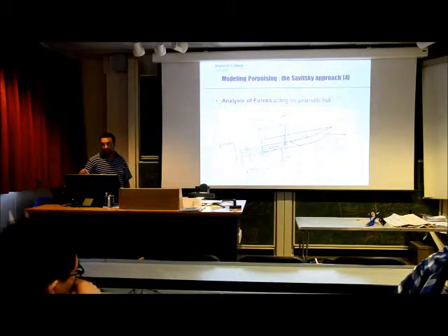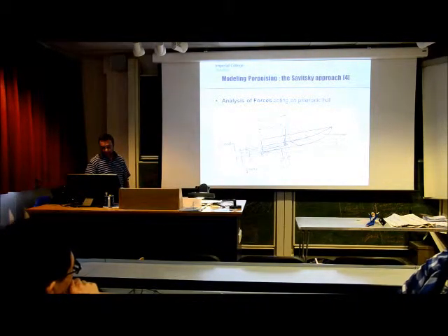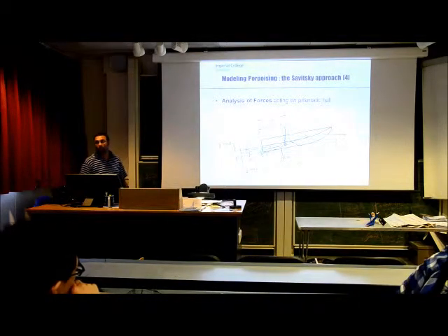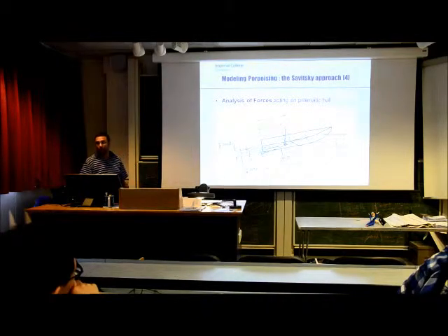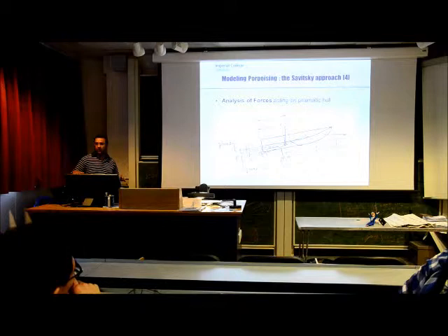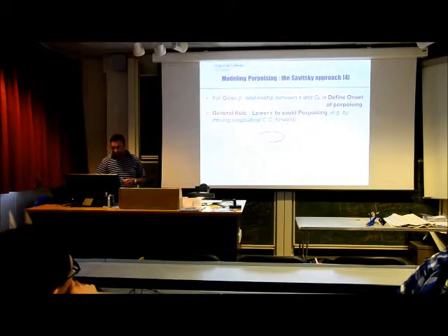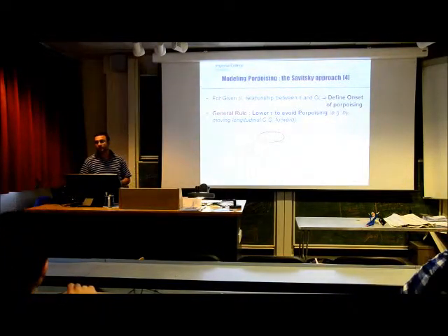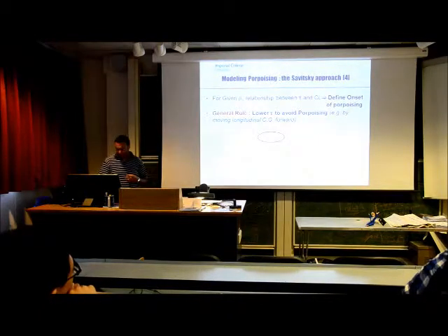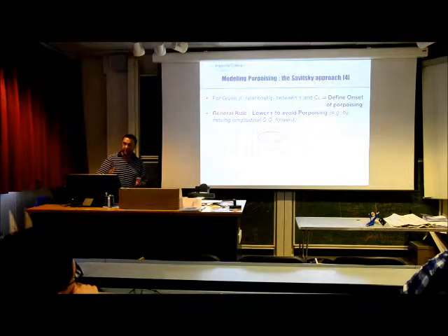I mean, any upward forces acting on the wing are accounted for, because this is like a racing boat model basically, and they have lifting devices as well. Okay, so that CL that goes in the graph is the lift coefficient associated with the bottom of the hull, basically. It refers to the water, right? The hydrodynamic one is the one giving the upthrust every time it sinks, basically displacing a volume and giving the upthrust.